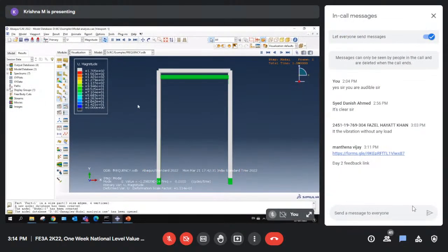And whatever the displacement that you're seeing here is only for graphical representation. Whatever displacement values you get during the extraction of the natural frequency won't be of any use, the magnitude of the displacement that you're getting. This is only to represent a contour and will not be of much help. So you can see different mode shapes from this beam section.